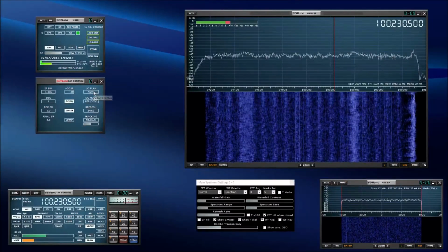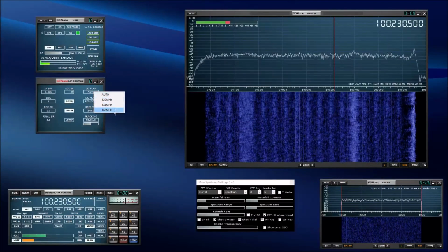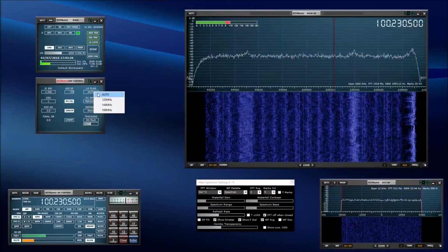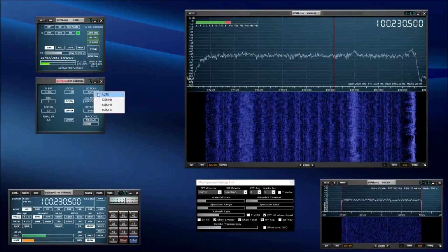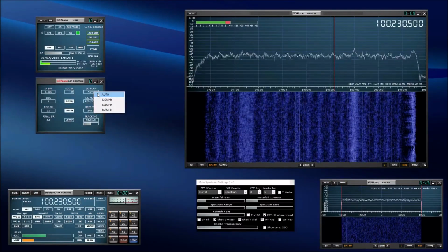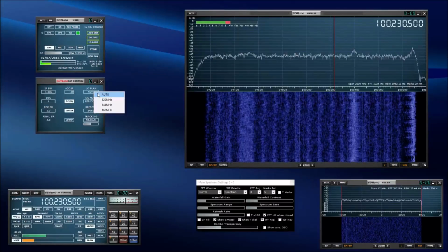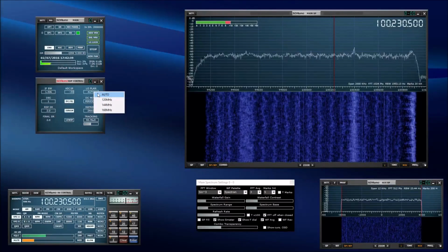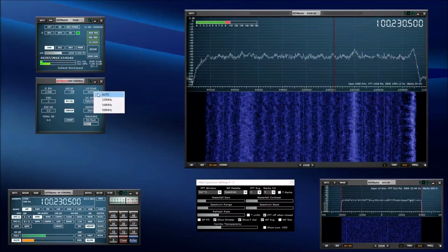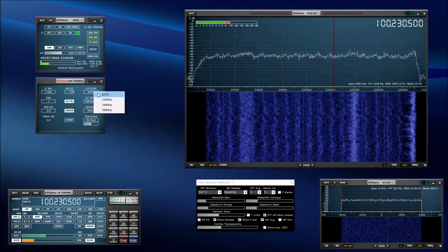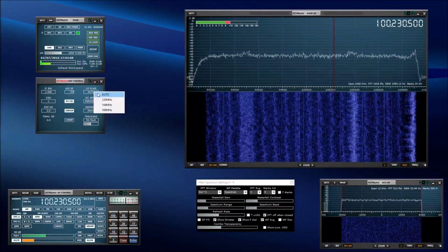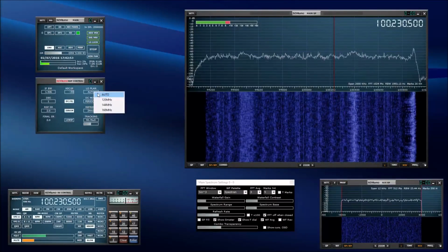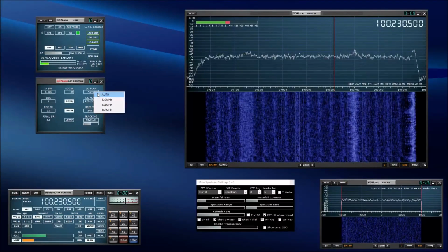LO plan. So this really, I don't really use anything other than auto for frequencies, I guess, between 250 and 450. If you have image issues or interference issues, you can try different LO schemes. We've got the three available there. If you find that auto isn't working for you, they do have different frequency ranges that they're optimal in. That's all in the documentation on the website. I don't have them to hand right now, but that's what that does.